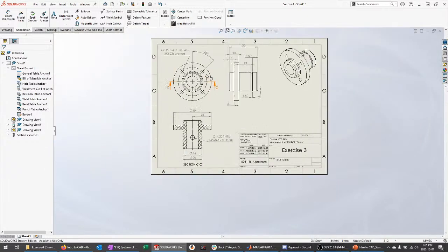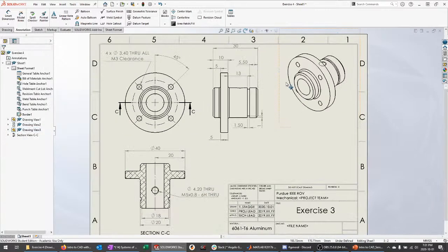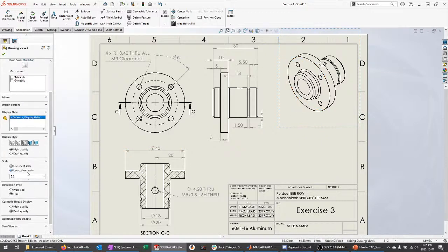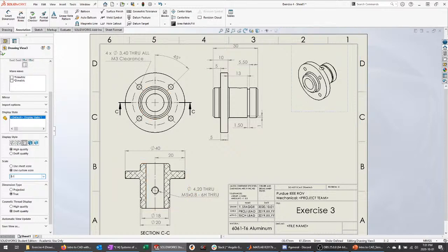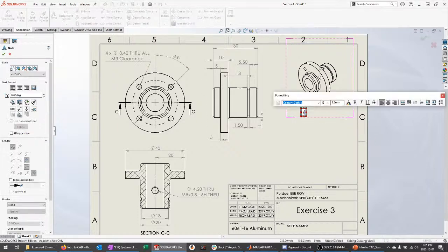That is important information to make sure is clearly communicated. For isometric views, you may occasionally change that to a different scale, just to make it all fit nicely on your paper. In this case, we wouldn't have to. But if you do something like that, I generally recommend adding a note that the scale of that individual view is different.